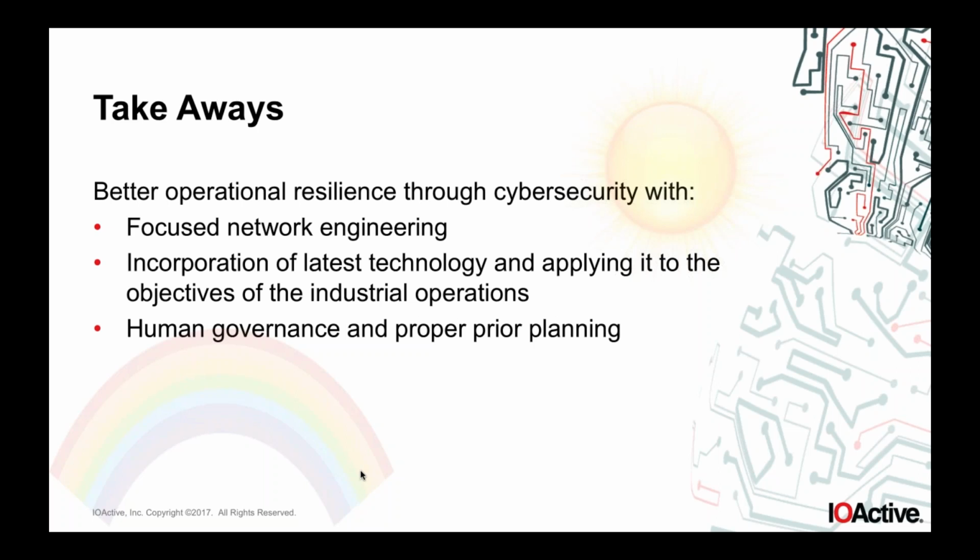And so what we've really tried to communicate today is there is a better way. Rather than being purely reactionary in the field of security and network design, you can align with your existing practices. You can throw in some additional things to do. We're already doing a lot of these activities anyway. Just go ahead and toss in the communications infrastructure data flow analysis, the requirements analysis, and then testing and commissioning, validating, doing vulnerability assessment and penetration tests on your networks prior to bringing them up live. Because at the end of the day, we're going to reduce your need to patch. The network is going to be focused upon its operational requirements, and communication data flows are going to be mapped and are going to be enforced electronically. So a lot of those things that come out there are not going to impact your process control environment as heavily as if it was just wide open with no planning and just, like I said, prior prop.